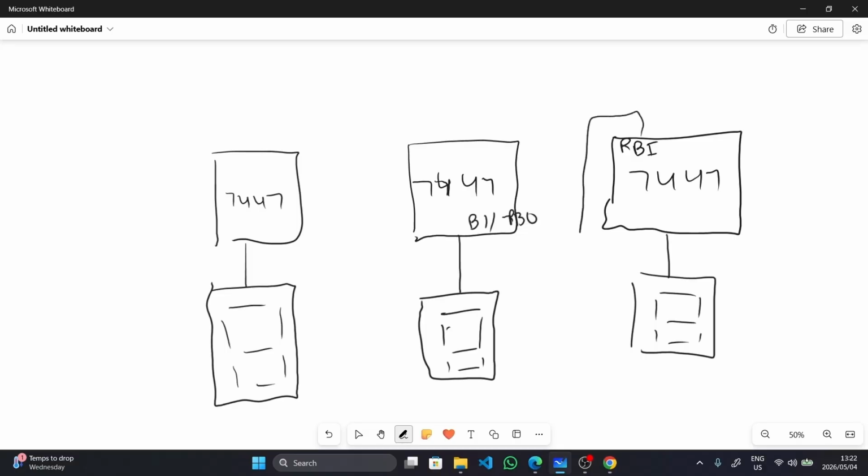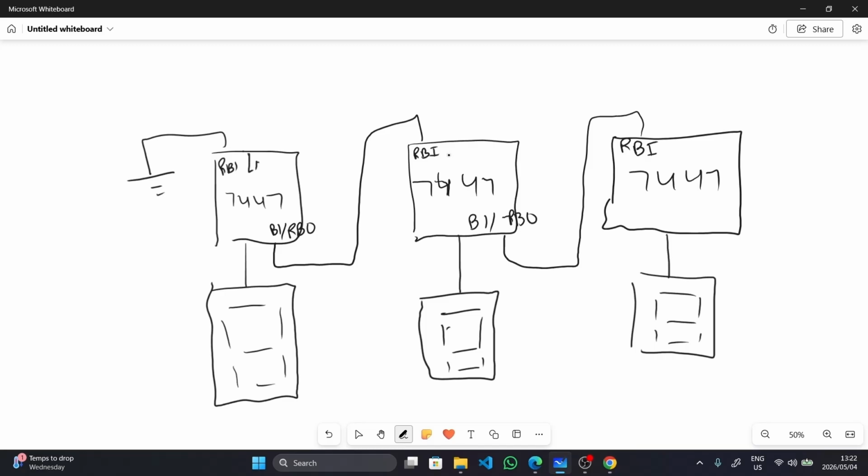So these two connect like this. Then you do the same. You have your RBI, and that connects to the RBO pin. Right, and then the other one RBI, this goes to ground. And then you can leave the LT pin just like that, or to cascade, but we don't do it that much. But when you do it, yeah, to cascade that.